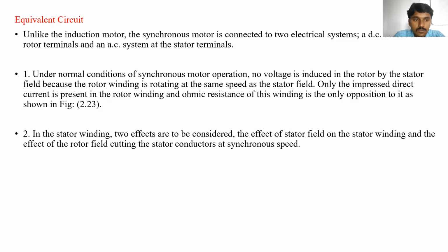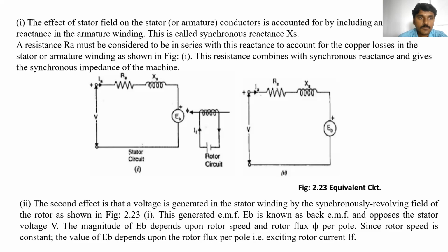Clear? One is the stator field, which is produced by the stator winding. Another one is the rotor field, which is produced by the DC supply, and this field cuts the stator conductors at synchronous speed.